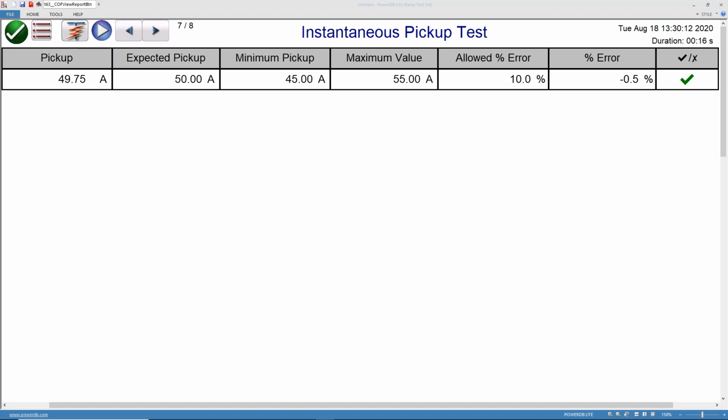So if you're looking for a 10% tolerance in your relay settings or in your test, then we want to make sure that we start our ramp before that. So it could be 15% or just somewhere outside of that tolerance band, because you want to make sure that you're actually getting a proper test on it and you're covering your basis with your tolerance levels.